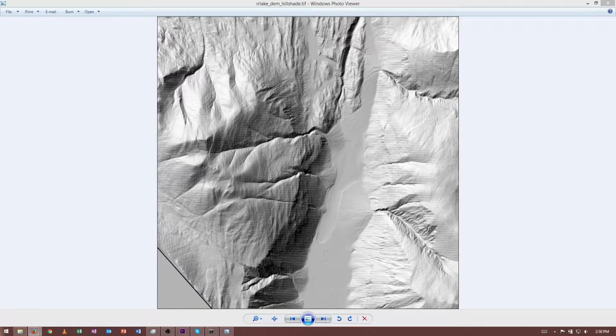We can see there's a fair amount of banding in this dataset. That's what these lines are from. This sort of artifacting can occur when a dataset is warped from one projection to another. The interpolation methods that you use can help to avoid such warping.